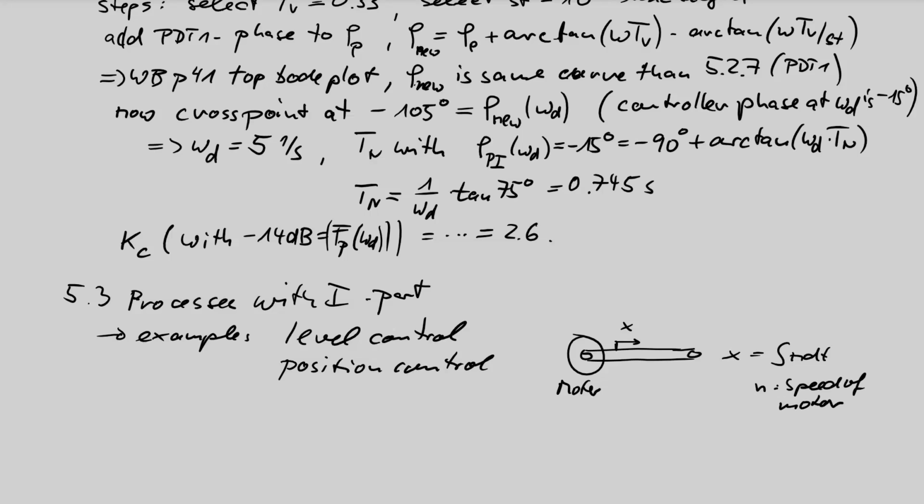So this is a typical integrating process, and in flying objects we have seen in other videos of my lecture that flying objects have 2 integrators in the process, depending, if you have a driving force, the force is integrated 2 times to get the position of a flying object. So we will very often find processes with integrator, so we have to check are there some differences.